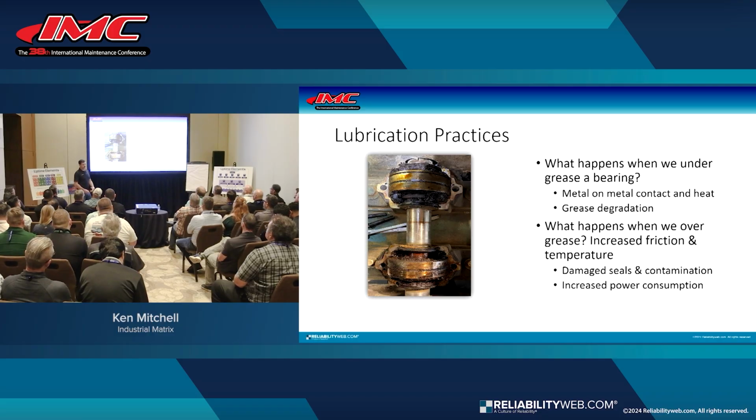So we move on. We've got the right grease, good storage, and good handling techniques. So what happens when we undergrease a bearing? Well, when we undergrease a bearing, we get that metal-on-metal contact. Those rollers make contact with the raceway. That generates heat. That also degrades our grease, because now that grease is doing a lot more than what it was designed to do. We're making it operate outside of its parameters.